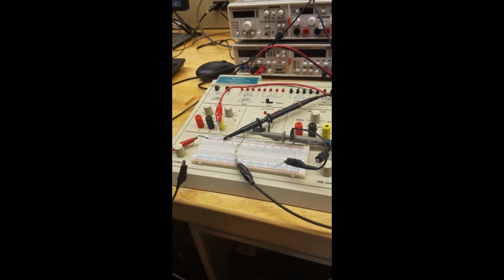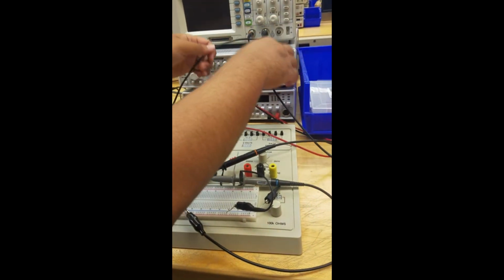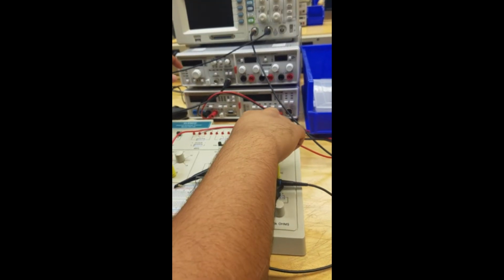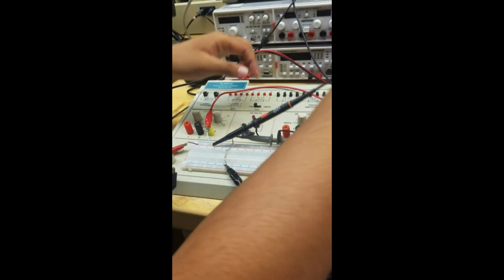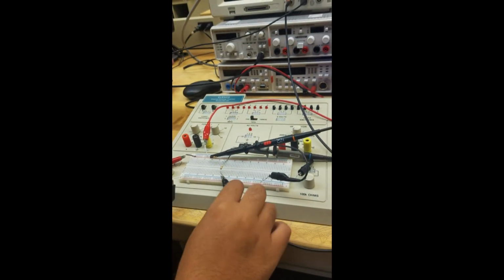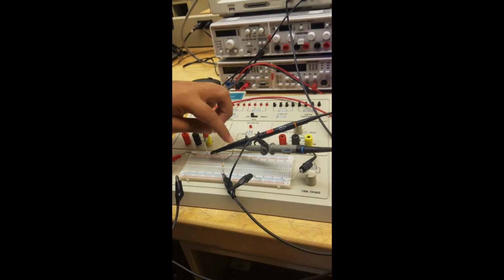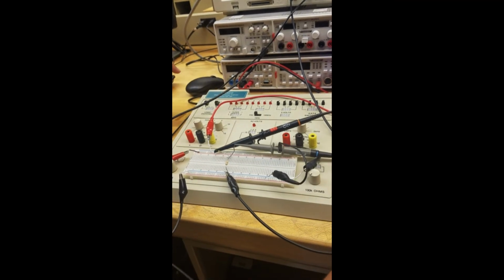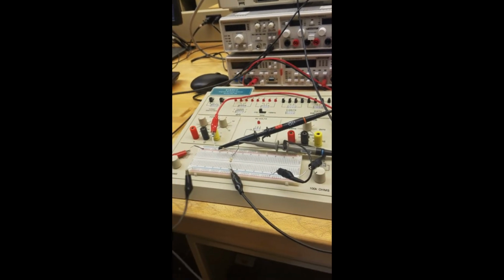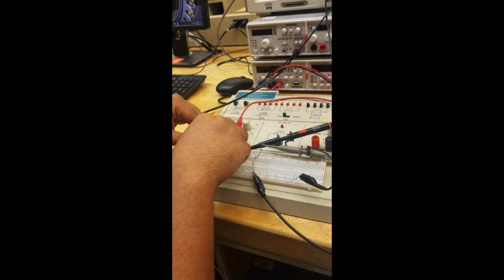You also need 2 oscilloscope probes, one to channel 1 and one to channel 2. Channel 1 is connected to resistor 1, the 330 ohm here, and channel 2 is connected to the resistor 2 area, so here and here, to measure resistor 2. And then we have our function generator probe, just connected here to supply the power. Oop, fell off.